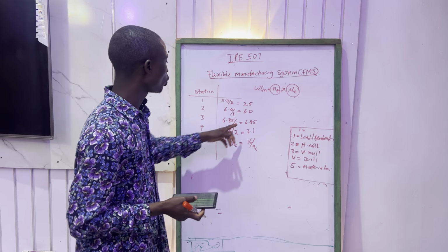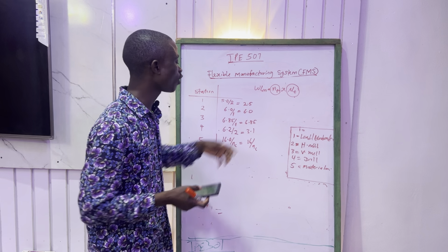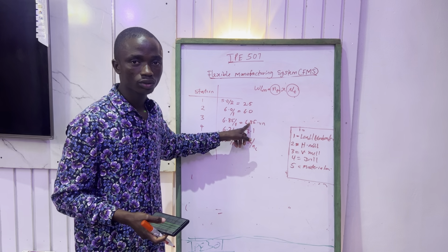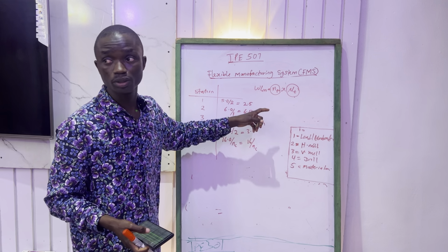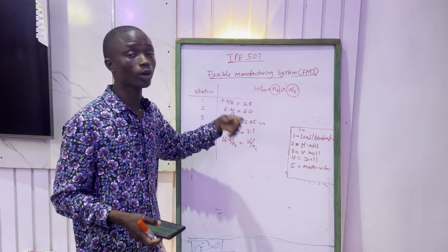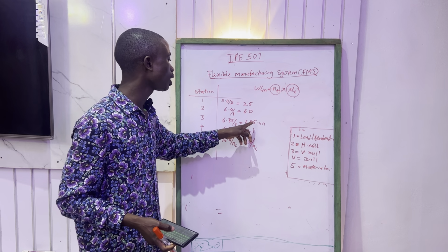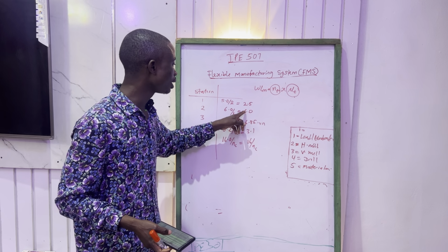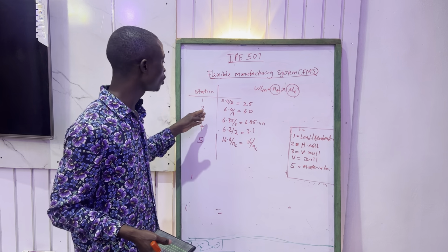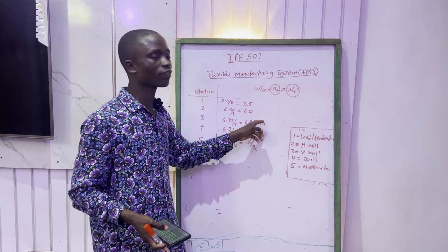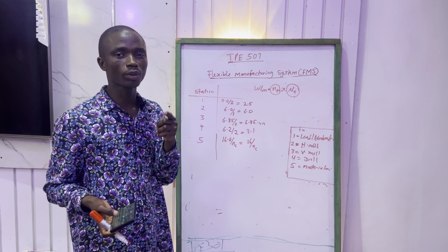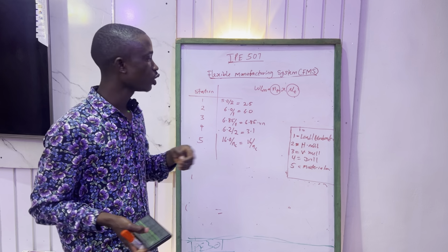One thing we should know there is that we have the bottleneck here to be 6.85 minutes. That is, all operations have to wait for this to complete before there will be assembly. This means the maximum time you can have in this production system for the workstation is 6.85 minutes. So for the minimum number of carriers, we need to equate what?